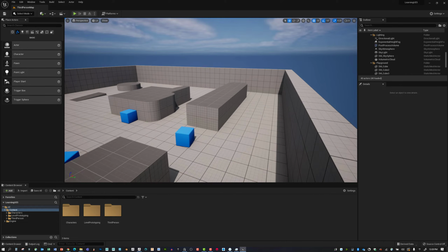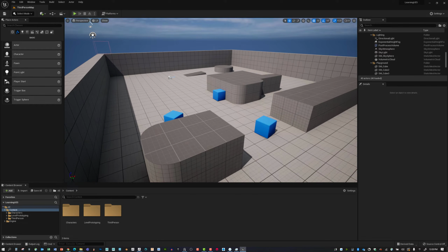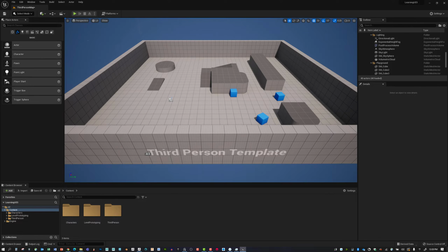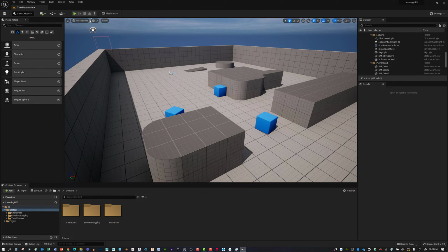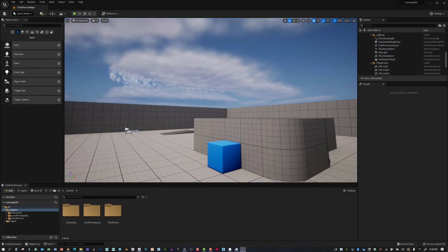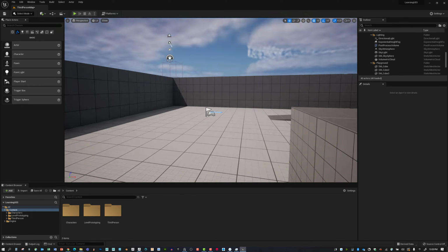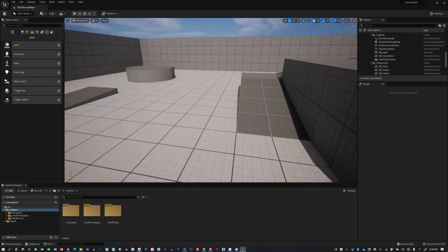And let's just say we choose this as a camera view and you like it. Now, because they've already got 2 camera views stored on 1 and 2, if I hold down Control and tap 3, while I'm holding down Control, that should add that as a new bookmark. So now after that's saved, I can tap 1, 2, and then 3, and here's my new view. And if we do the middle mouse scroll wheel, you can zoom in like that. So that's another way that you can kind of move through the world like that.